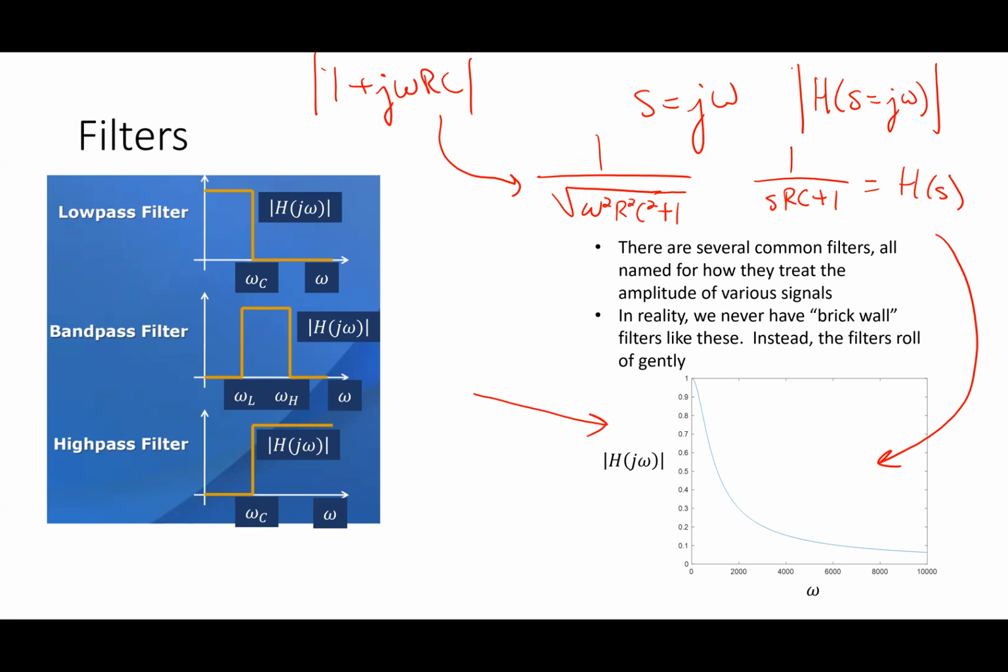What does that imply? S in general can be anything. You learn Laplace transforms with unit step functions and all sorts of crazy functions, right? What we're saying is, in the special case where I have a sine wave as an input, s equals j omega, and this is basically the exact same thing as impedance analysis, and I can look at this to understand what the magnitude and phase change is in steady state, right?